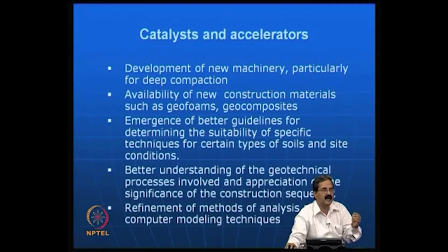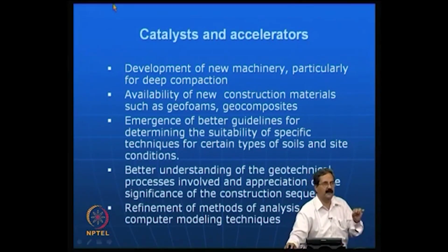As I just mentioned, if you want the bearing capacity, you know C and phi. Then you get a bearing capacity, use a factor of safety of 3, and with compressibility, like compression index, you calculate settlements. That was helpful. But if you want to really model a construction sequence, knowing C and phi will not help. You need to use constitutive models to model the sequence, because sequence is very important in geotechnics.